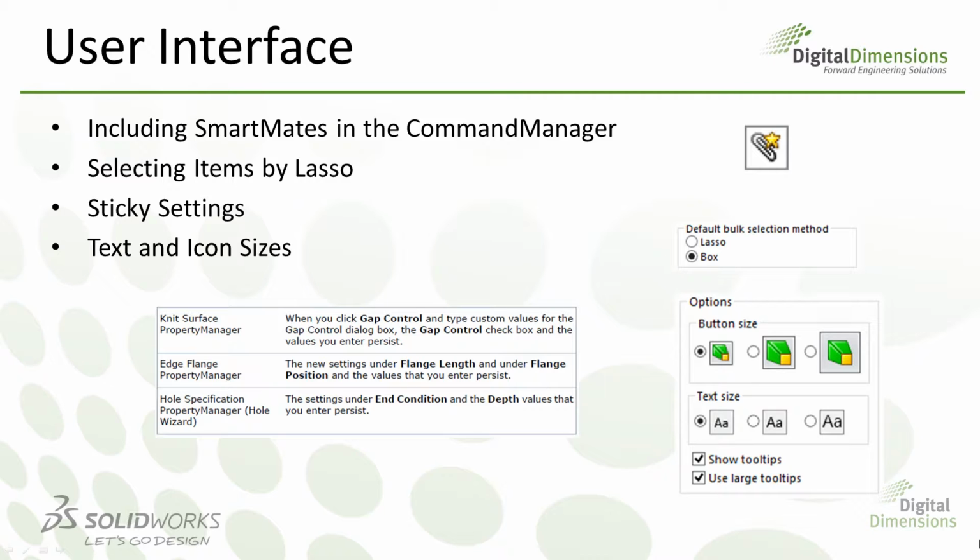The sticky settings enhancement in 2014 basically just refers to the property manager settings for a lot of the features and operations inside of SOLIDWORKS. And what this does now in 2014, there isn't really much to show here, but a lot of those settings are going to be remembered between sessions and between features.